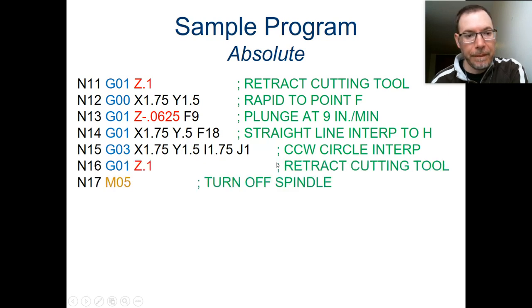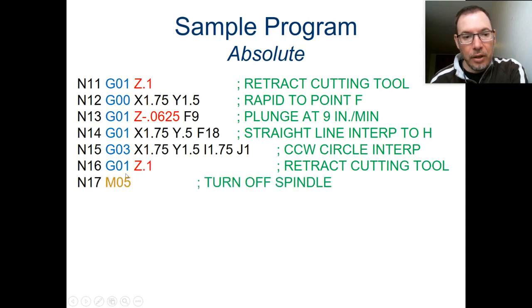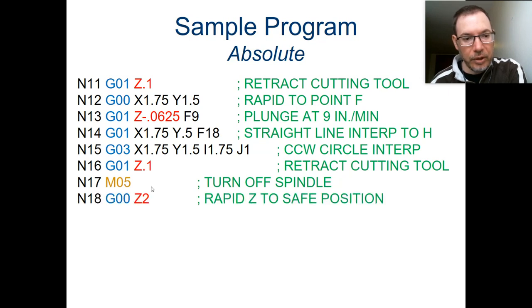So just be aware. We definitely want to make sure we're putting this in correctly as far as it being a center point. All right, and then next line, now that we've completed our letter, we're going to come back out of the part. So we're moving up to our safe height again. Turn off the spindle because we're done cutting. And so this is the other part that we do. We have a beginning part that we do every time, and we have an ending part we do every time. So our ending part, we're going to turn off our spindle, just make sure we're safe to go on to our next operation.